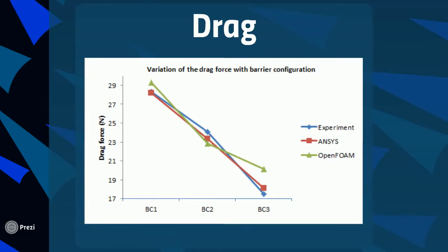As the angle decreases, the meshes become more difficult to accurately construct. OpenFOAM is very sensitive to mesh quality, much more so than ANSYS. So simulations using low quality meshes are likely to yield results less accurate than those obtained using high quality meshes. I should say at this point that the same mesh files were used for both ANSYS and OpenFOAM.